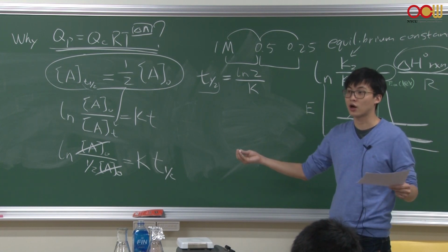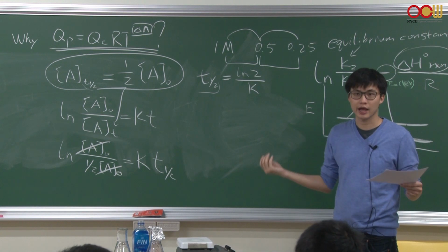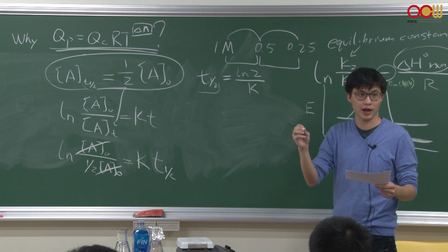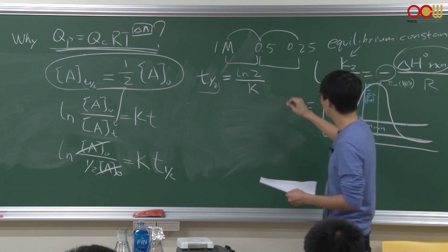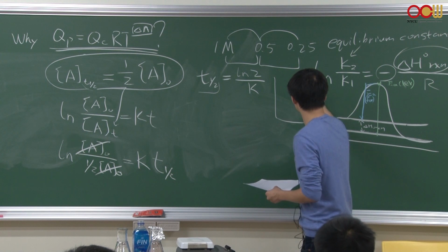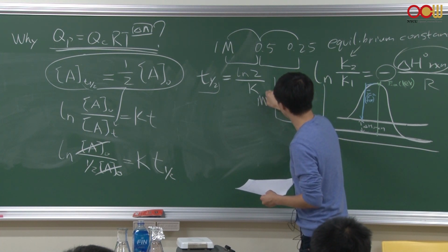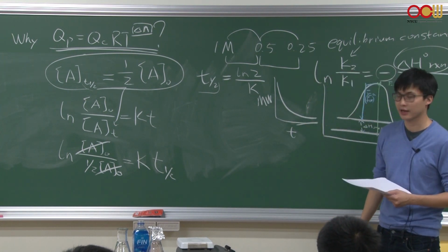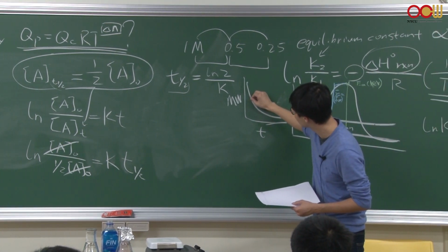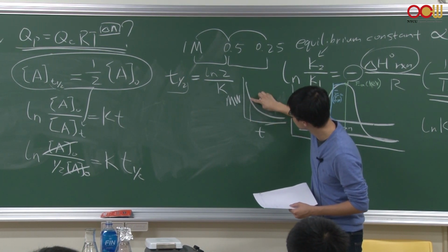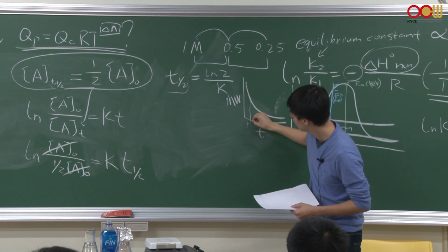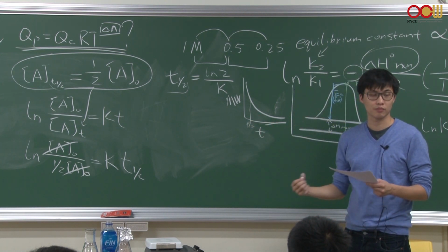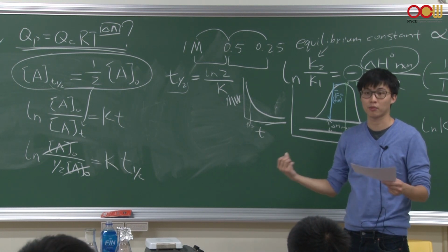Because when we're dealing with a long chain polymer, I have a certain technique where it preferentially breaks at the middle of the chain, all right? So over time, my molecular weight, this is molecular weight with time, I can get a plot like this, and I can figure out where my half-life is. So let's say this is half of my molecular weight. Then this is my half-life for this polymer scission process, which means polymer breaking.